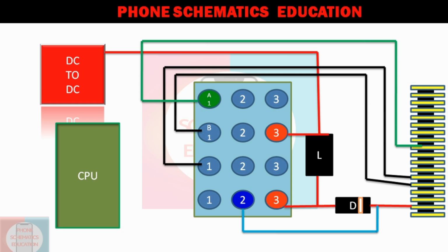I will tell you. Suppose a phone comes to you for a waterlogging reason or any reason, and there is no display, I mean a blank display. You know your phone is turning on, either by connecting your charger, or checking your ampere meter, or from vibration or bell, by any method. Still there is a blank display. But when you focus a torch or any flashlight on it, you will see some graphics or faint graphics. That means there are graphics.